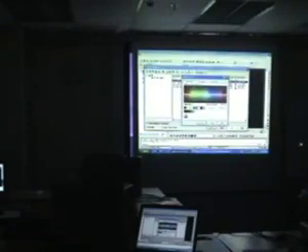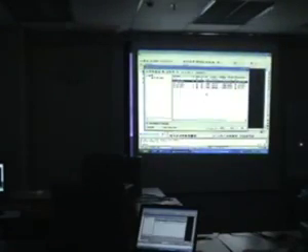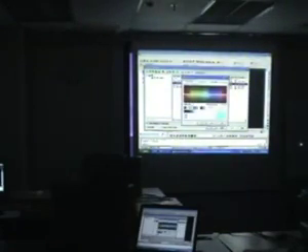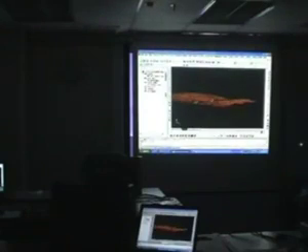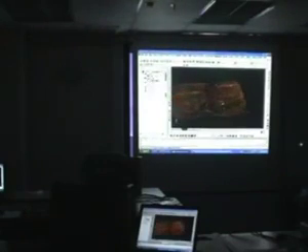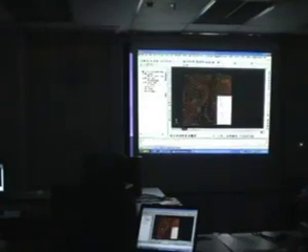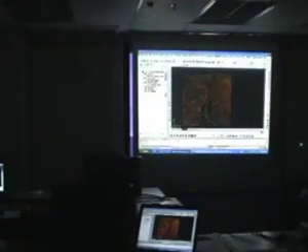So let's say if I want to change the color, see the major lines, I'll put them as green. Switch minor maybe to red. More visible difference. So you can actually see the contours minor and major. Again, they are also in 3D. So if I orbit, you can see them in 3D. It's not so apparent as the triangles, but you can still see them in 3D. So I'm just going to reset the view back to the top plan and zoom into the contours.